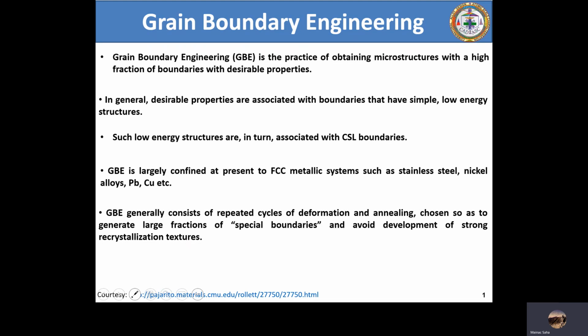So definitely, when we have a grain boundary engineered microstructure which has a large fraction of special boundaries and a reduced volume fraction of high angle boundaries, which unfortunately cannot be completely eliminated, it's very hard to do that, nearly impossible rather, the chances of preferential corrosion are much lesser. Okay, in special boundaries or the coincidence lattice boundaries, as you can say, associated with the cubic materials.